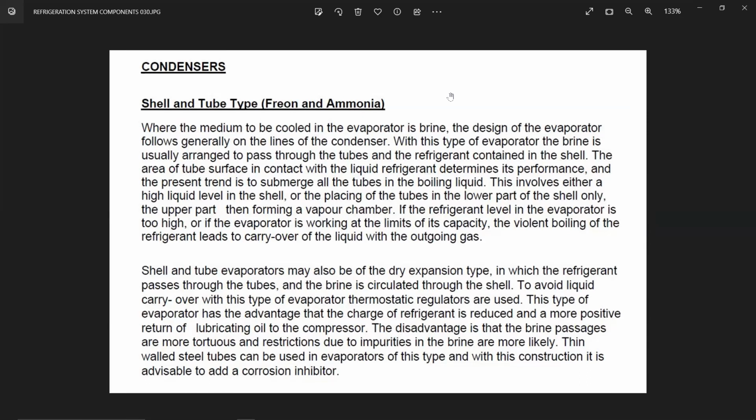It is a liquid of a known density, but generally it is a saline solution type of liquid. Like, it is salty in nature. Nowadays, you're having brines which are not natural brines. You can have water-based brines. You can also have brines which are mixed with two, three different chemicals, water-based only, but again with some other chemicals added to aid the heat transfer and everything. Simply, a glycol solution is also considered brine, right? Glycol is also considered brine, but then you require a huge volume of it.